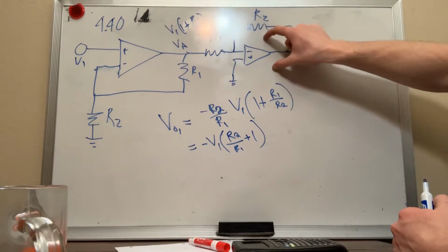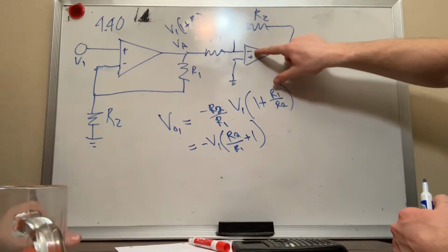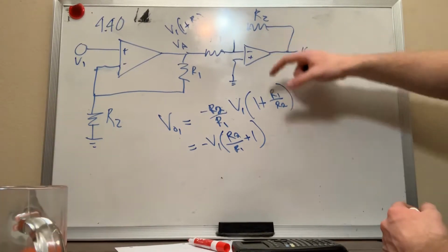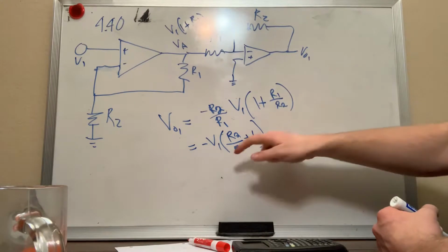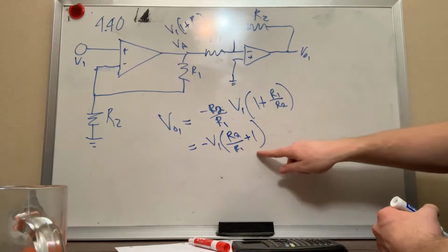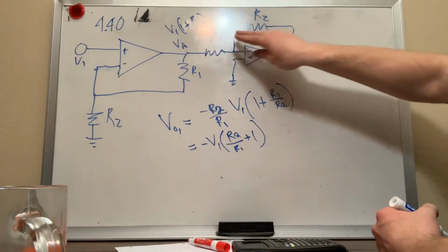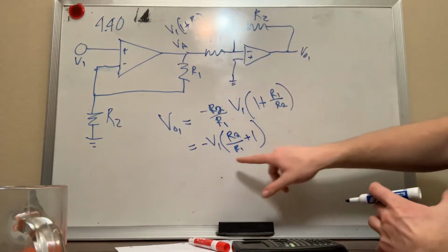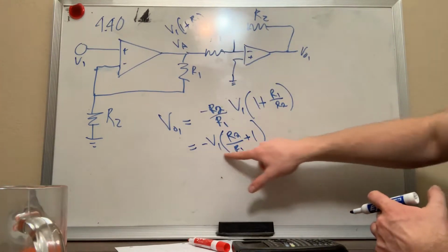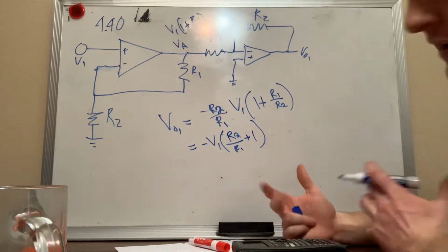And then the gain of an inverting stage, where the source goes into the negative input, is the feedback resistor divided by the source resistor, but it's the negative of that. The resistor values are kind of confusing because here you have R2 and then R1, then R1 and R2, so you can't really see it, but the form at least looks good, right?